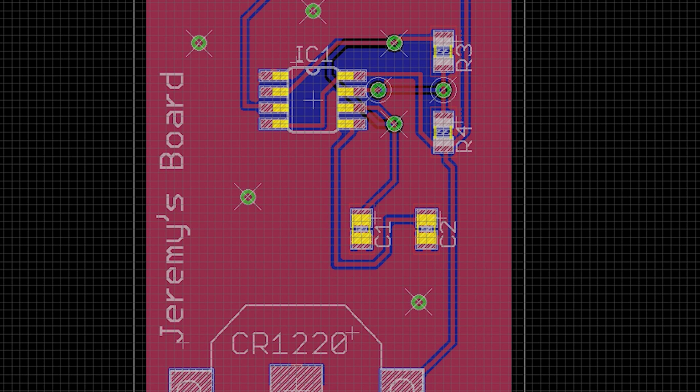If you want to take the next step and actually have the board assembled for you too, that adds a ton of additional cost, but it's pretty common practice with larger quantities when you want to start mass producing things. At that point, you would want to output the actual solder layer as well, that specifies the solder paste layer, which specifies where paste would go down from an automatic paste machine, so that then a pick and place machine could automatically place parts appropriately. And that adds an additional layer of complexity as well that I won't dive into in this video. But that's basically the gist of it.